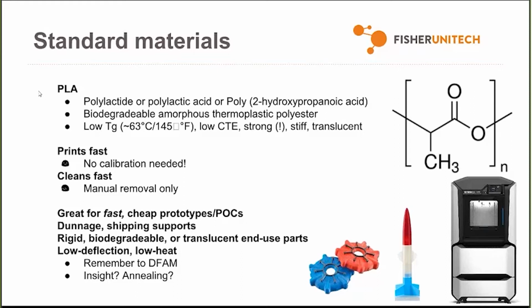On an F123 series machine, you will need to swap the print heads in order to run PLA. I took it apart and I checked. The model tip is a little different, and you'll actually replace the support tip with a cooling fan. That process on the F-Series only takes about 2 minutes. And the really nice thing here is, since there's just one tip, there is no need to calibrate that machine. You load the material, which itself takes about 30 seconds, and go.